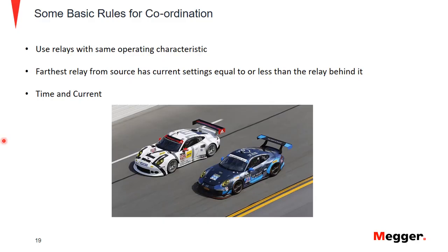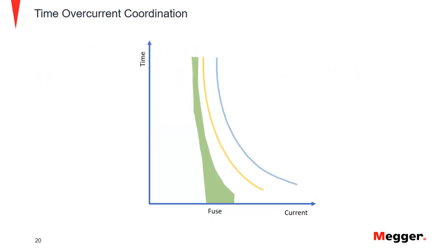So let's go next. All right, so in the coordination example, we're going to line out a couple of examples here. So the first one is we'll actually throw in a fuse. We actually have a fuse damage curve here. We also have our normal feeder that we had earlier in our main. Still, again, inverse time overcurrent. So we're still talking about the same current, same TCC. We're still talking about the same style of inverse curve.